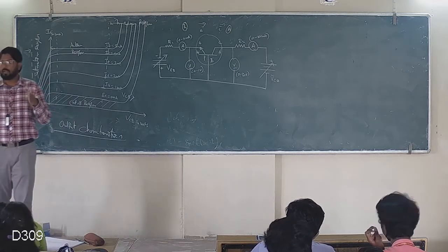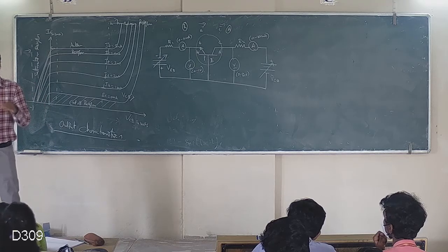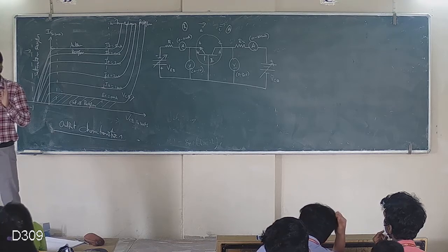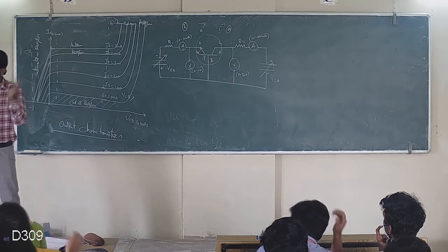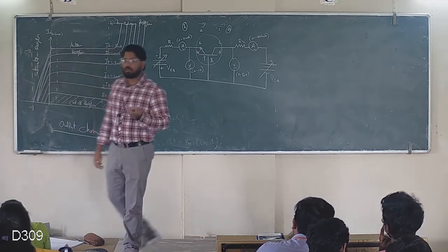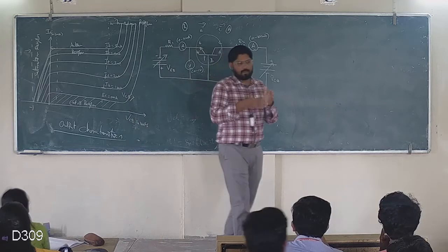We never record information in the fourth region. Why? This is the region where the device gets damaged. Permanent damage occurs at the junction, which means the transistor loses its originality, NPN or PNP.